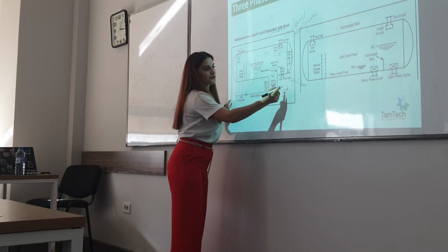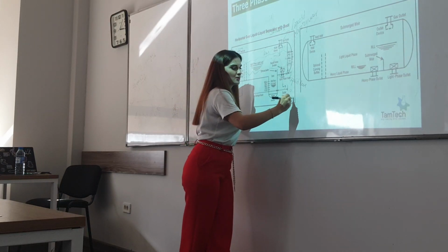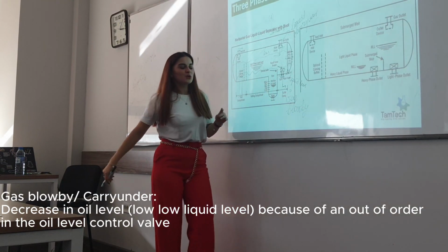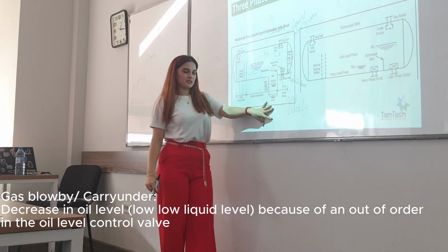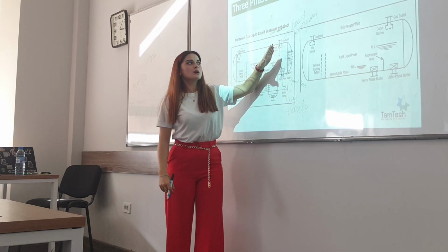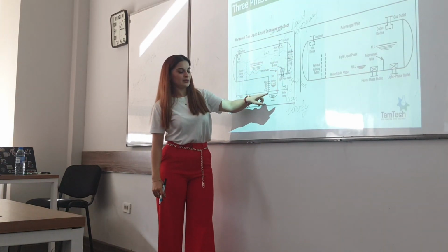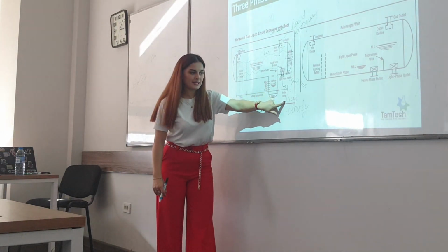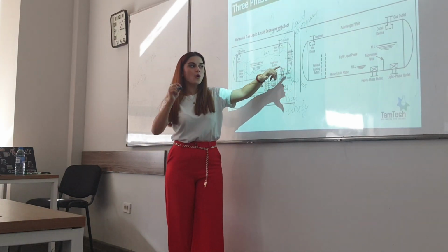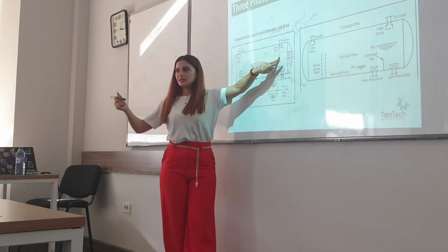The vice versa case, if gas goes out from the liquid outlet, is called gas blowby. Most people confuse these words, but liquid going out from the gas outlet is liquid carryover, and gas from the liquid outlet is gas blowby. Gas blowby happens at low liquid level, and liquid carryover happens at high liquid level. Is it clear?